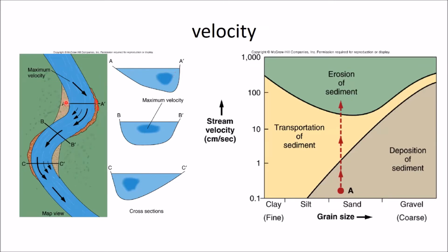So normally we have the plane, the sediment accumulated here. And in B, the velocity is highest at the center of the channel, and therefore it is equal on both sides and there is no lateral erosion. But here at the C cross section, again on the left side the erosion occurs, and on the right side, the deposition occurs.